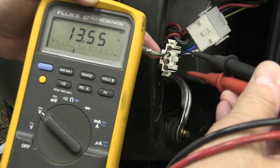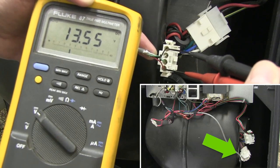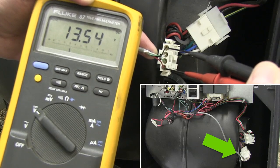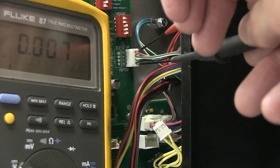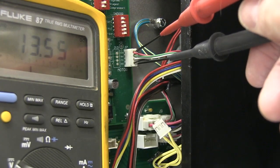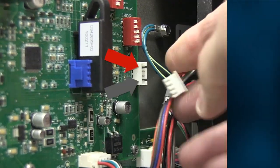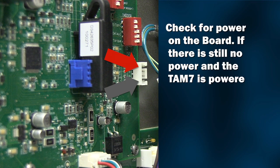Next, verify that there are approximately 13.8 volts DC across the red and black leads on the low voltage side of the motor. If you don't have approximately 13.8 volts DC, check the source on the AFC board at plug J7, again across the red and black leads. If you do not have power at plug J7, remove the plug and check the pins on the board directly.